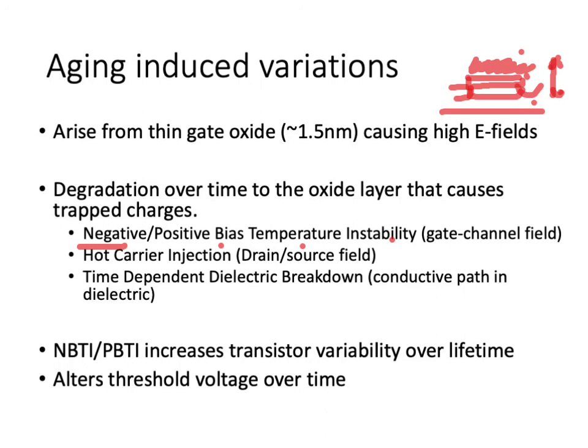And there is a third mechanism for this oxide degradation. It's called time-dependent dielectric breakdown. It is the existence of free charges within the dielectric, and then when you start applying an electric field, and the electric field is typically quite non-uniform because of all the various channel and gate engineering, this leads to the charges actually creating a conductive path within the dielectric, and this causes the TDDB mode of breakdown.